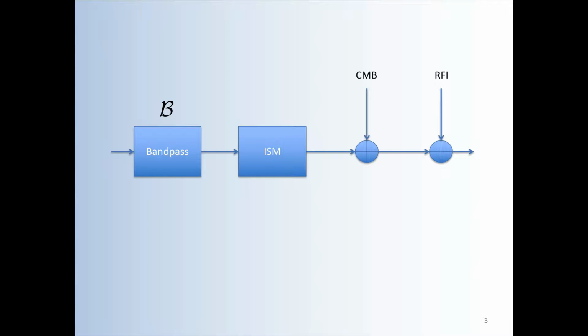We like to abstract a communication to what we call a channel, which in this figure is the relationship between a baseband signal, which carries a digitally modulated waveform, to a baseband channel at the receiver. Now obviously there will be modulation up to passband at some frequency that's friendly to communication through the atmosphere and through the interstellar medium, and then demodulated back to baseband at the other end, but we're omitting those modulation-demodulation steps.